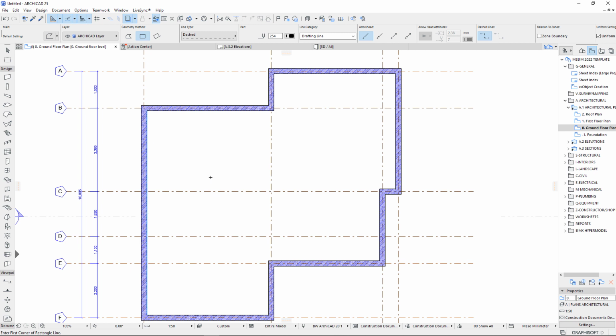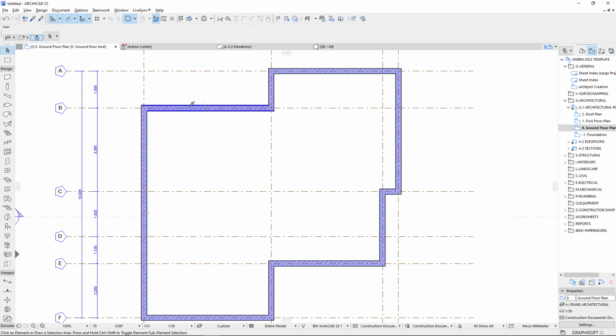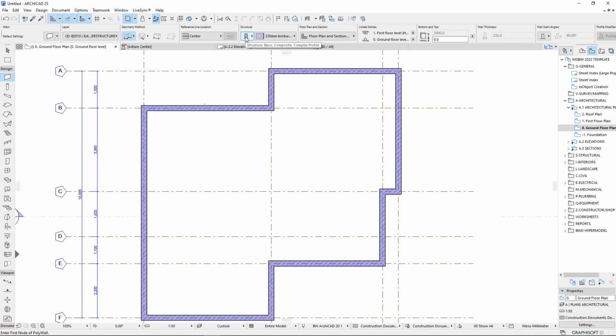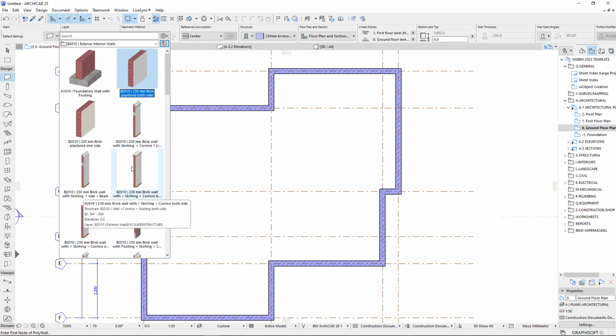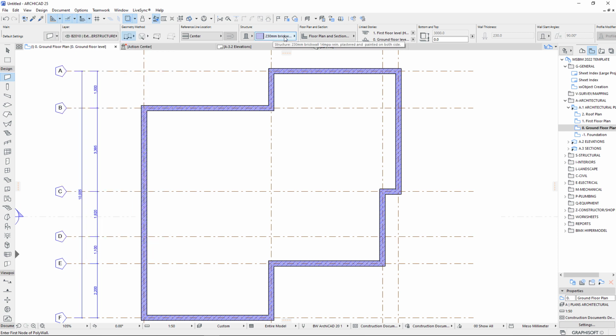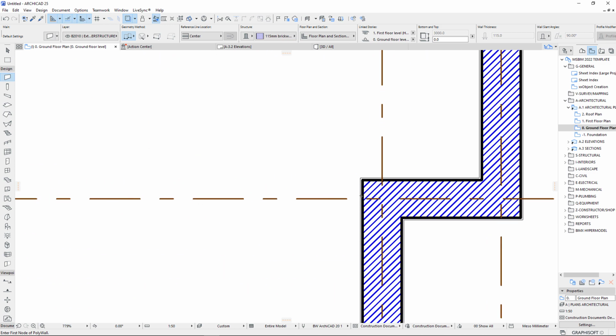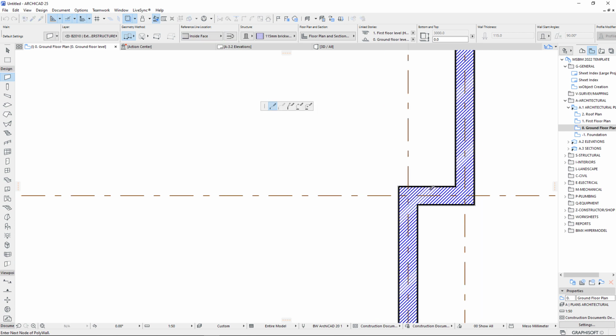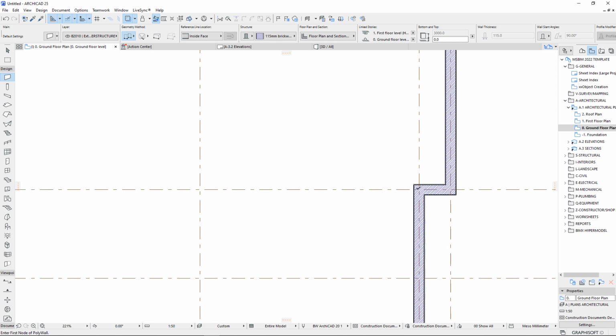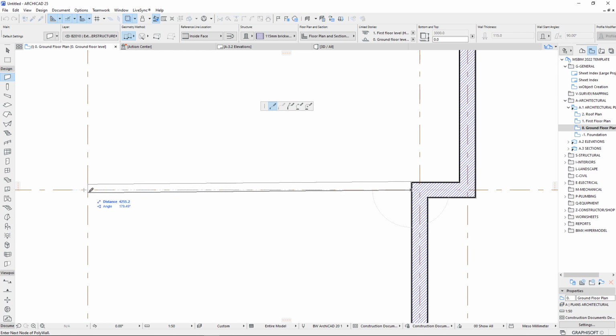So what I need to do is the interior walls. I'll still use the same tool. Let me just pick the parameter of that. I can use the favorite for that, but I can also use the structure under the list of composite. There I can go for an interior wall. I think I have just a 1-on-5 brick plastered and painted on both sides here. Because this is not a structural wall, I won't use the center of the wall as a reference. I'll use the inside of it, so that I can just draw it like that. Oh, sorry. You've got to be precise and clean.